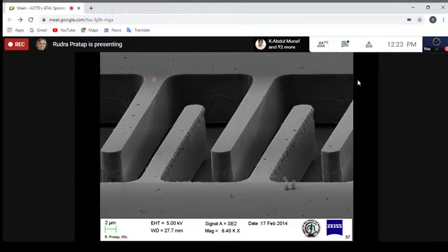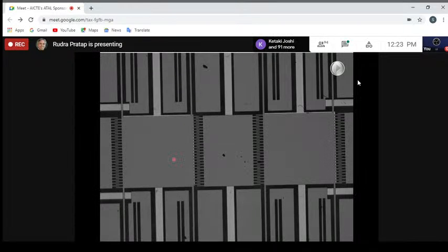So suppose that this is grounded and you have applied 5 volts on this, then you have now electric field between this and this, and there will be a fringe field which will pull this finger in this direction, right? So the whole structure will get pulled. I don't know if you can see on your screen that this structure here is actually moving, right? Both these proof masses are moving. The motion is very small, and therefore you may or may not be able to notice it.